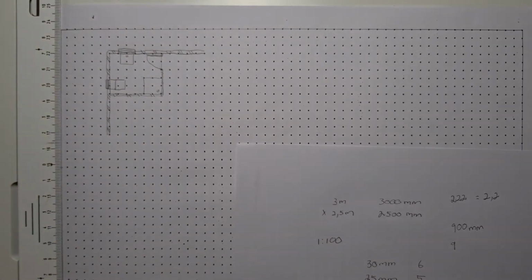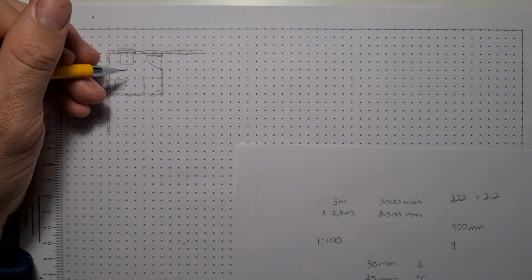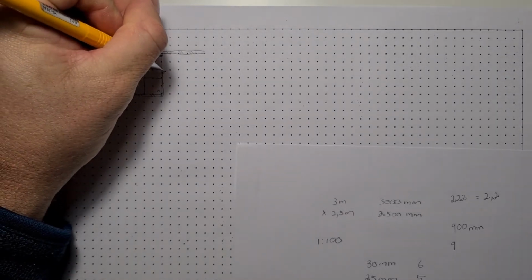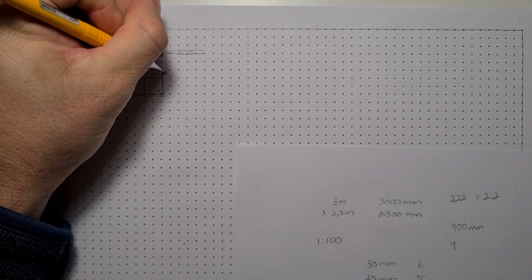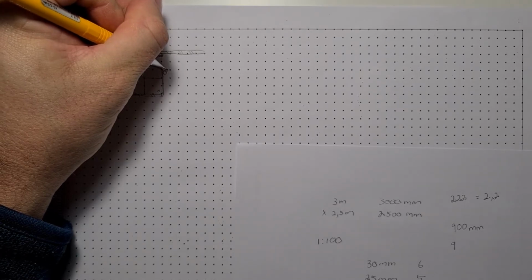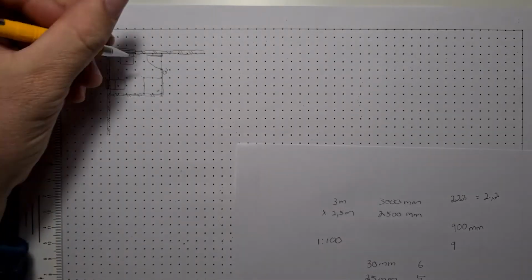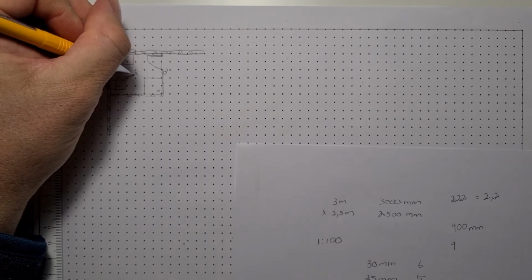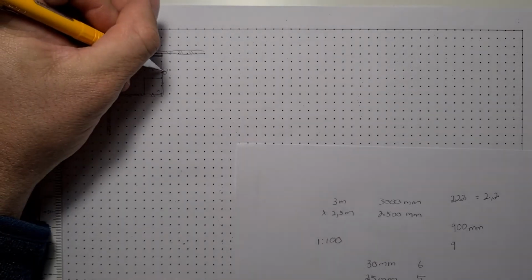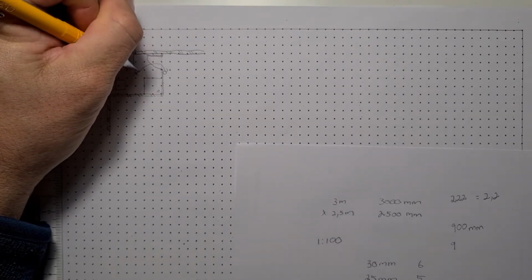Right, and there's my hatching done. Then we also have to add in our electrical symbols. With this being a bathroom, it's better to put the electrical light switch on the outside. I'm also going to add a ceiling light, and then just draw in the connection